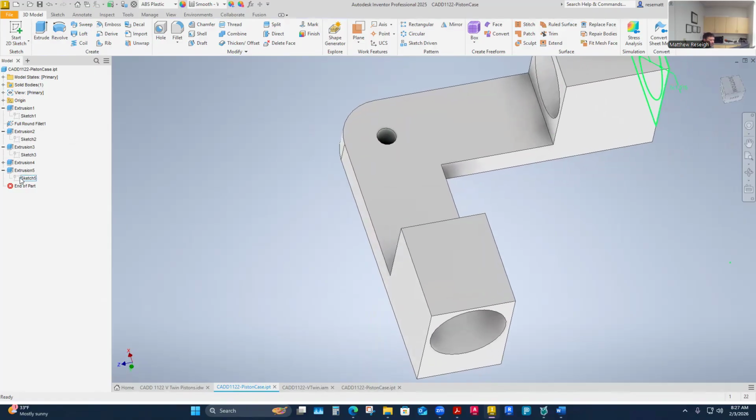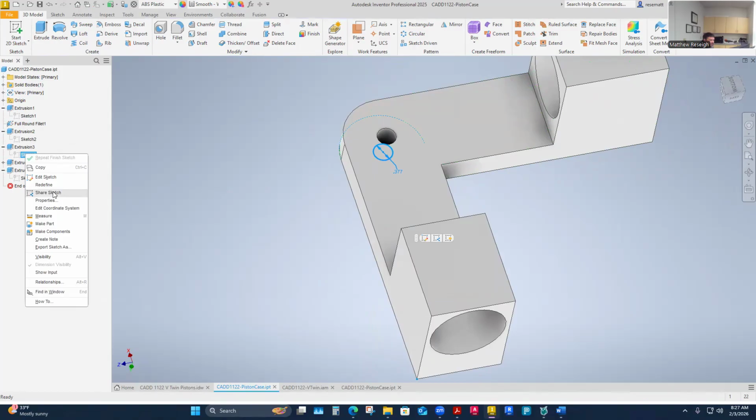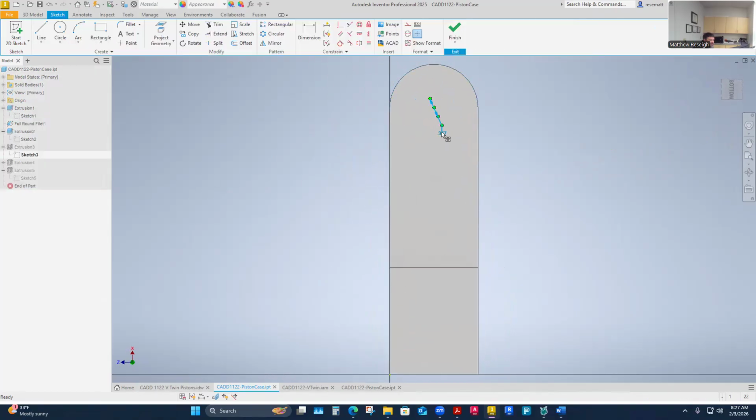So I'm back. What it's going to be is I find my sketch here, go into my sketch. Let's fix this thing. Instead of my weird equation, I'm going to say the real dimension, 0.375. And then I'm going to add my tolerance in here, which is 0.1. Oh, sorry, 0.01, 10 thousandths. It would look like that, but 0.01 is 10 thousandths.